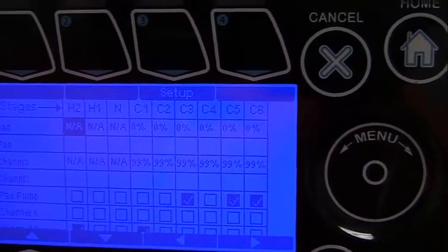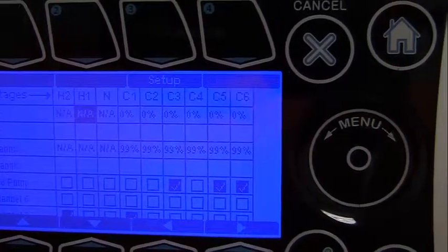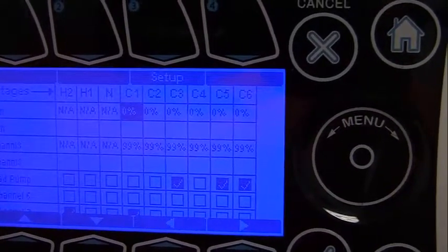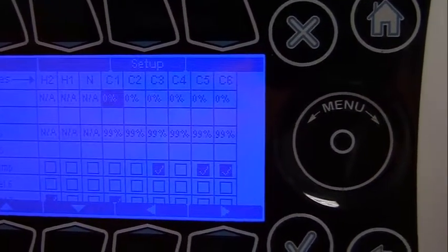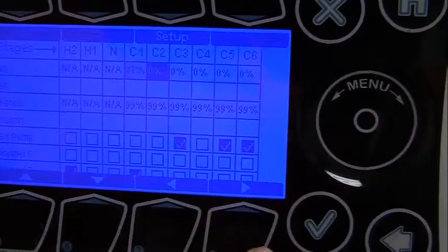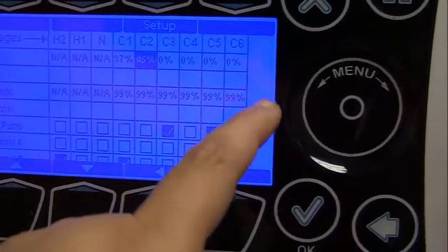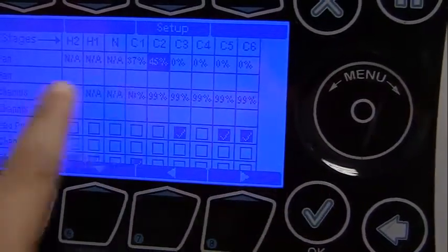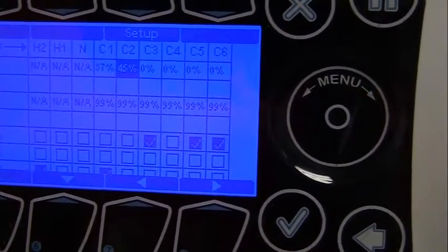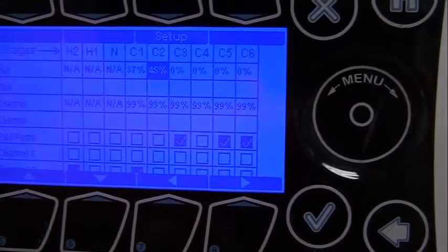Right now, what we'll do is scroll down to cooling stage 1. Since we have our cooling stage set up at 78.1 degrees, I want my fan to go on, and then go to cooling stage number 2. You can do that for your fans. If you have vents on here, you could do that as well. You could also check on the ones that you want for the other channels as well.